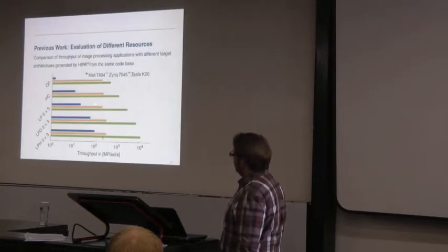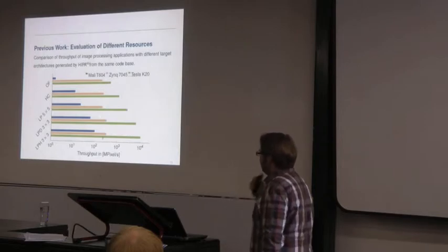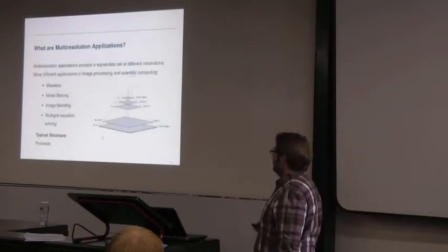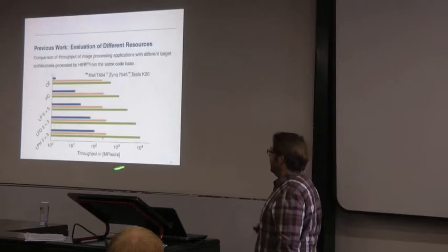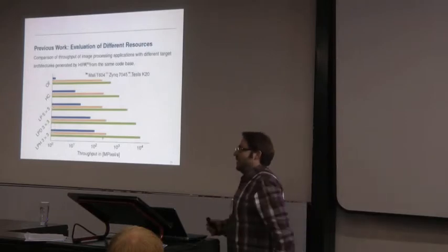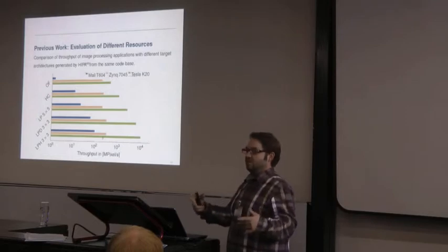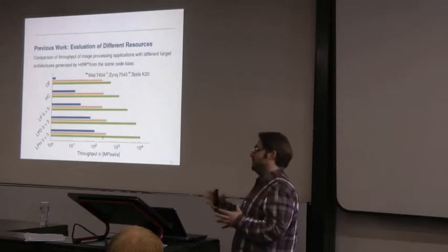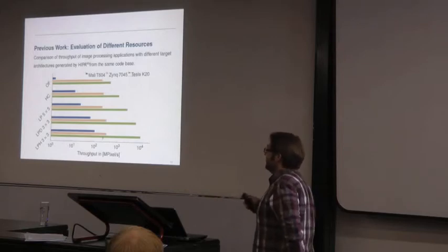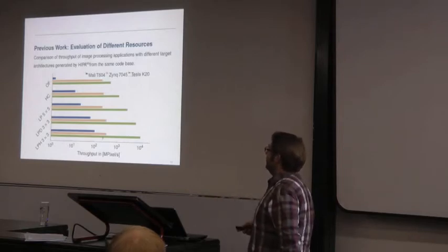So, I mean, there's some difference, but mostly what you can see from here for FPGAs, as long as you can cram the logic all into the FPGA, mostly what decides its performance is the number of iterations that you have to do, unless you find a way to get that number smaller. But that's mostly what defines the throughput that you can get on the FPGA.